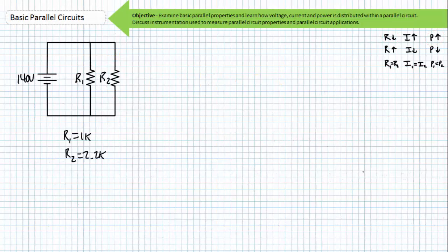Again, that last illustrated problem should have been readily solvable given your understanding of voltage, current, and power distribution inside a parallel circuit. Some of the questions being asked in this and the previous example problems did not require any calculations, but rather gauge your feeling of how circuits like these operate. Does more or less current flow through larger or smaller resistors with the same voltage drop across them? Does source current increase or decrease as resistors are added or removed from a parallel relationship?